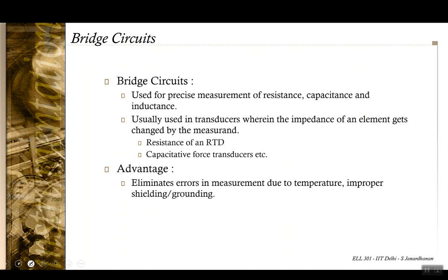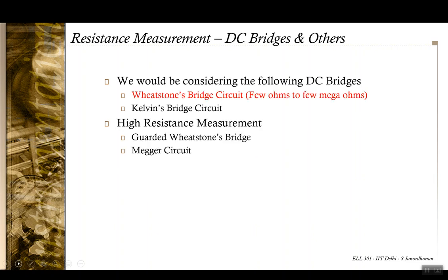We had seen the Wheatstone's bridge and come to the conclusion that, due to the way the components are connected, the Wheatstone's bridge is generally useful for measuring resistance from a few ohms to a few mega ohms. In case of low resistance, we need to look for other options.